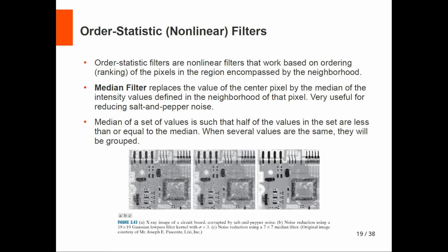On the other hand, you have to consider that Gaussian filtering is one example of a smoothing filter, not the only possible way. There are much more advanced filtering techniques that not only can get rid of the noise but also preserve the details and the sharp transitions in the images. So only consider the Gaussian filter and the median filter as two basic filters with nice properties, but they are definitely not the only types of filters that we can have in image processing.